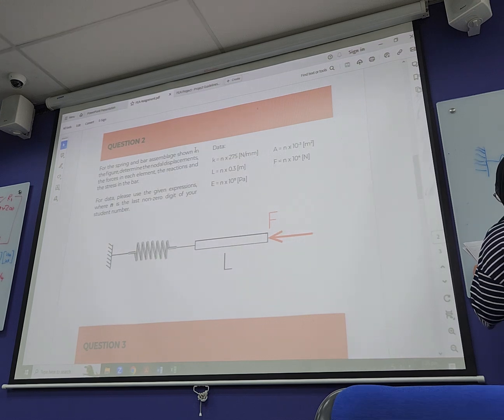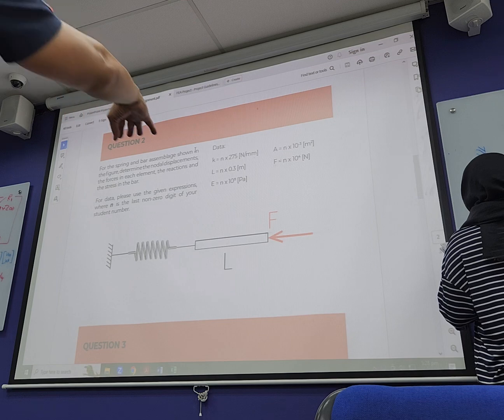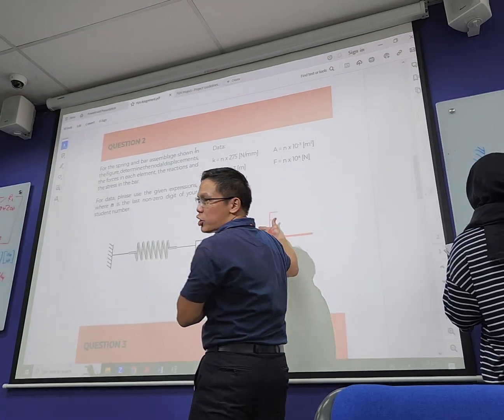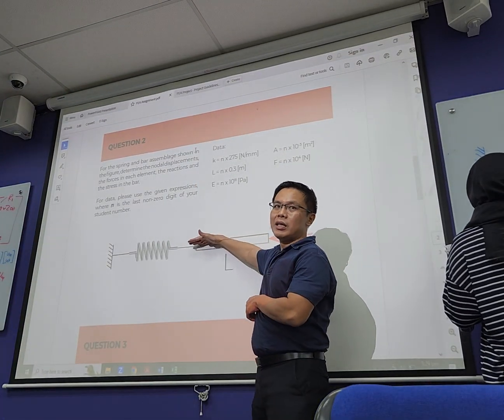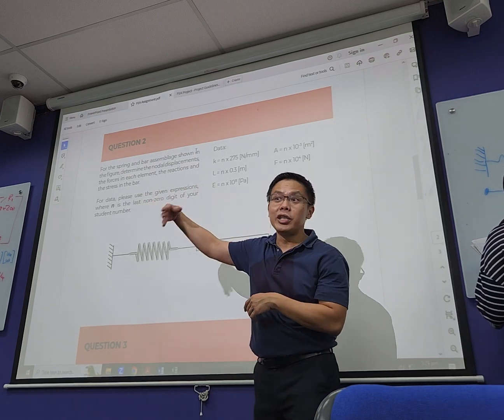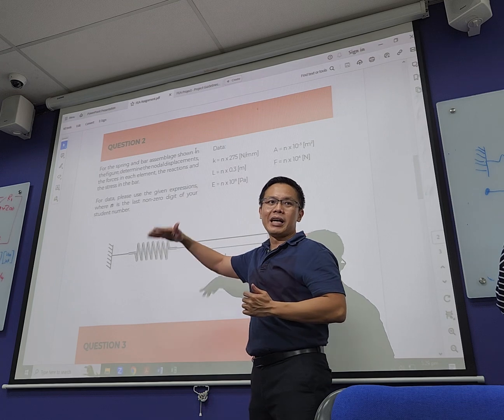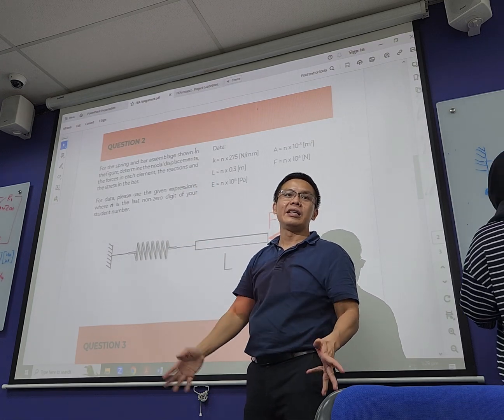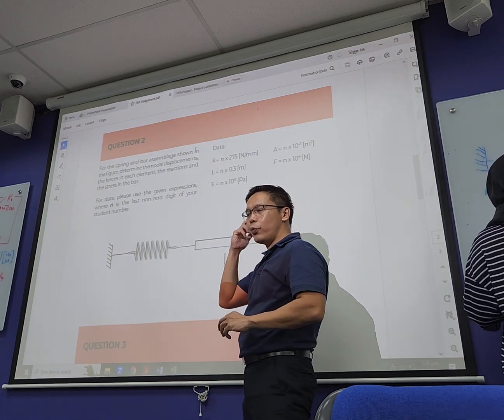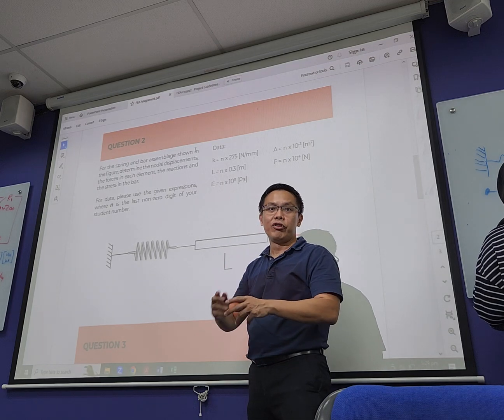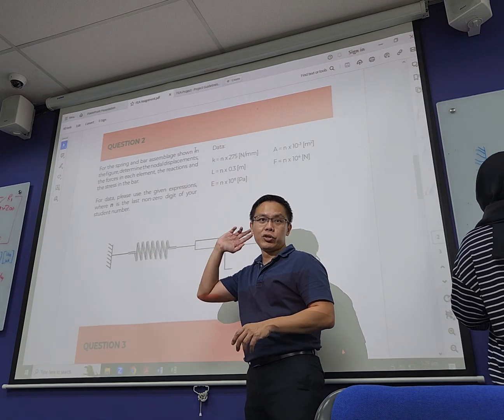Same thing, imagine if this is the actual condition, you expect things to what? Imagine that push this right, this will flip out in real life, correct? This one you will see some sort of lateral torsional buckling going on. In this case, no, because we are only applying a single degree of freedom, which is tension or compression, so it will not flip out.